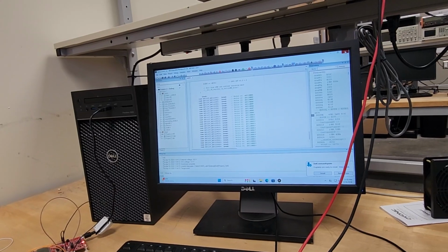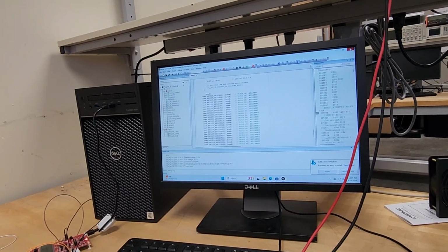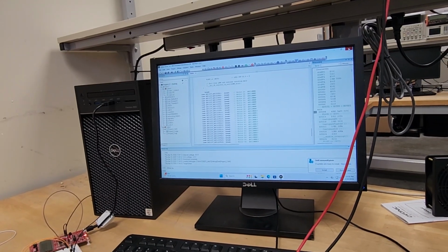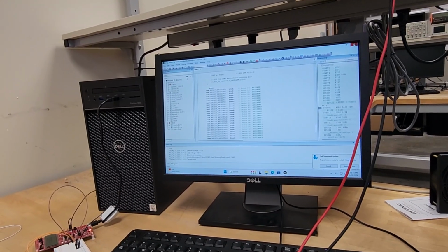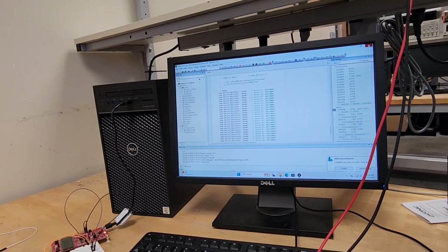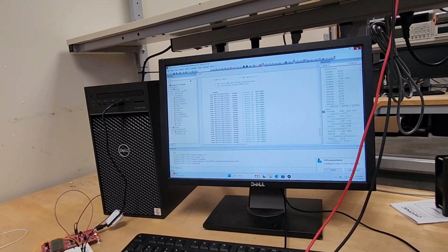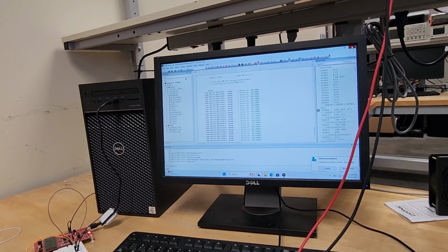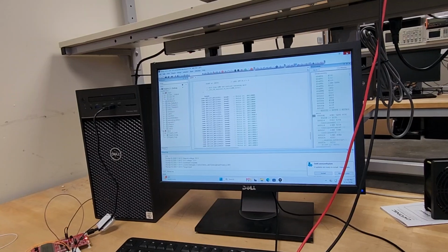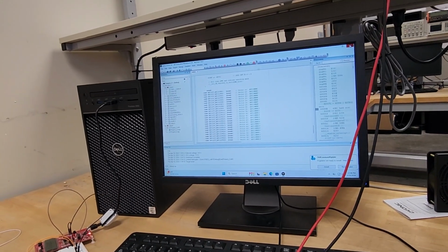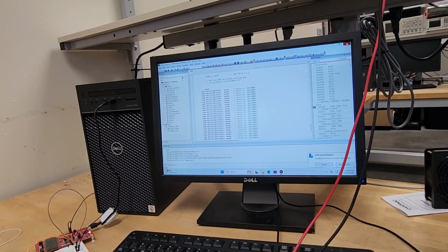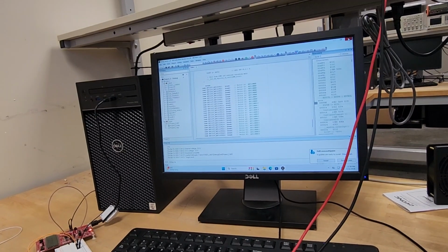The temperature is split into integer and fractional digits. Each digit is written to the LCD segmented memory, so the temperature appears on the display. This entire process repeats once per second, creating a continuous real-time temperature reading. In addition to the basic operation, like I said before, the accuracy of the measurement depends on 3 important error sources, which were the R naught error, the T naught error, and the V reference error.